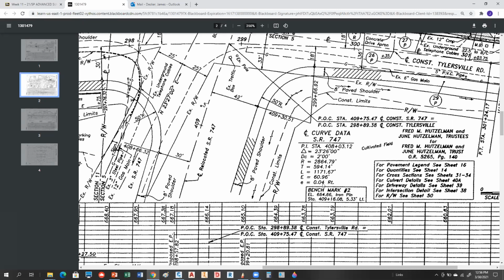But they do have what's called your super elevation rate. And that's the maximum rate that it occurs. So basically your roadway is at a 4% grade across it. That's pretty steep, actually. If you were sitting at a stoplight on an icy day and you were just sitting there, your car may actually just kind of scoot off to the right, because at 4%, that's pretty steep. Okay, you kind of get the idea?